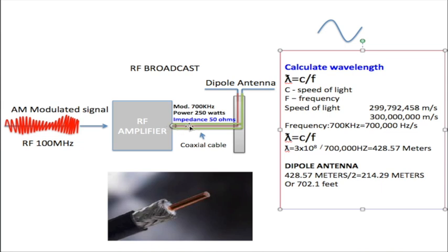So the analyzer will be right within the circuit measuring the amount of signal that is being reflected back. You see, if you don't have the right amount of impedance, part of your signal is going to be reflected back towards your amplifier, and this analyzer would measure the amount of signal that would be reflected back. It will show 1:1 as a rating on the front of the analyzer, right? 1:1 will simply mean that 100% of your signal is being sent and radiated out.